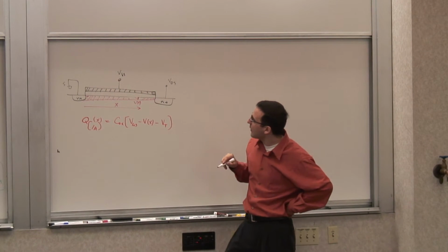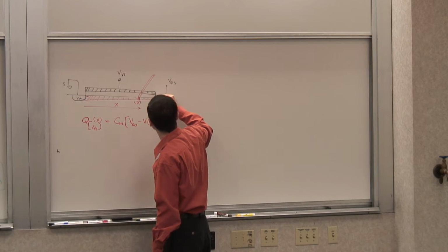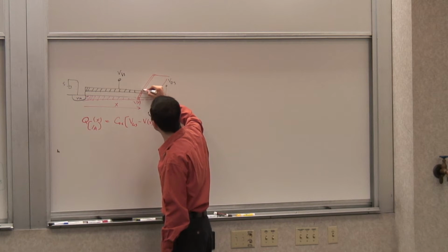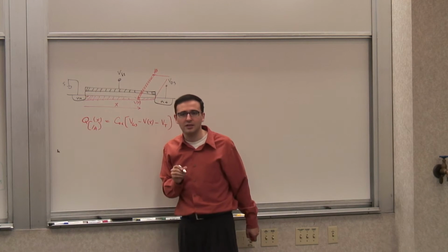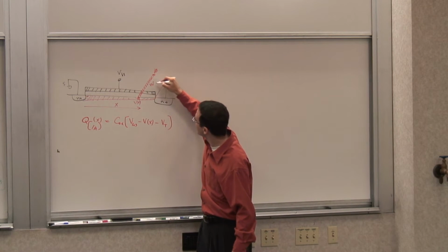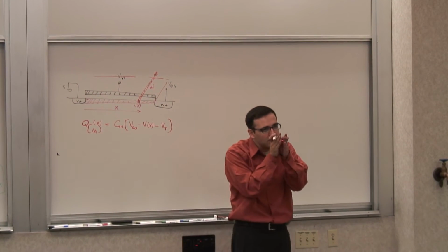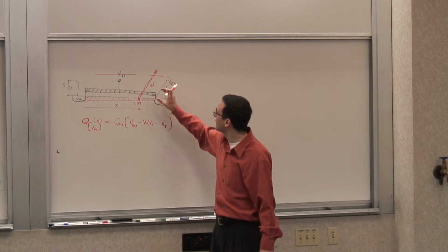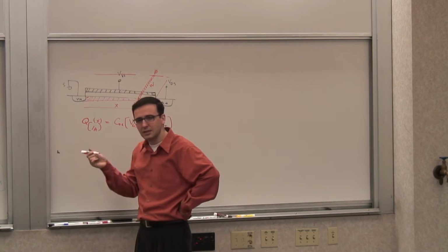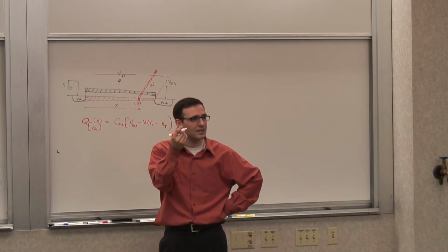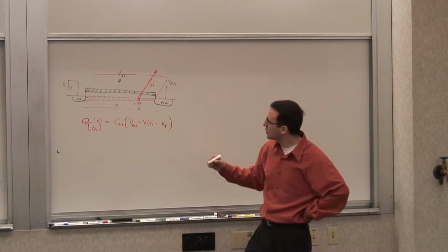So now, if I were to break this transistor into little slices, so they are sliced in this direction, so this is the third dimension, right? So let's say I have a little tiny transistor here. Think of it as, let's call this dx. So the channel length of this tiny transistor is dx. Its channel width is the same as this transistor's W, right? So all the same across. So I have a tiny transistor there with a channel length dx and width W. Within that transistor, I can still assume that the electric field is constant, right? If it's an infinitesimal transistor, it's a good assumption. And I can use that model, basically. So what is the dq?